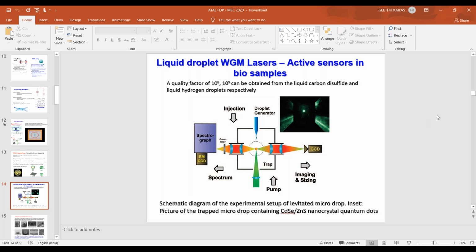I have done one experiment which made use of a hollow fiber coated with a gain medium inside, a micro ring embedded. There are a lot of modes available initially, but when we increase the pump power, the side modes were suppressed. This is because the normal WGM modes are not applicable here, but the WGM is actually converted to two modified WGMs.